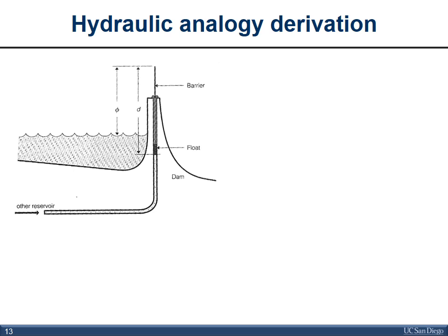Effectively what we can do is modulate the height of this barrier from some other reservoir, some other energy source, and use it to control the rate of diffusion of water vapor molecules going across the dam. So what we can say here is that the current is going to be some reference current I naught, e to the minus q(h1 minus h2) over kT.